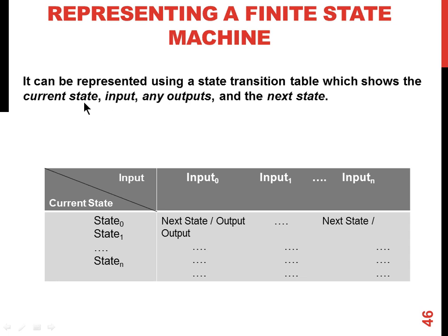And then it goes from that state to the next state of the finite state machine based on certain input combinations. And the outputs are generated when it is in one of the selected states. So each state, depending on what it is, output can be generated in a particular state. So it goes from state to state to state. Again, once the transition is over, it will go back to the reset state and stay there or wait there till the next input comes.